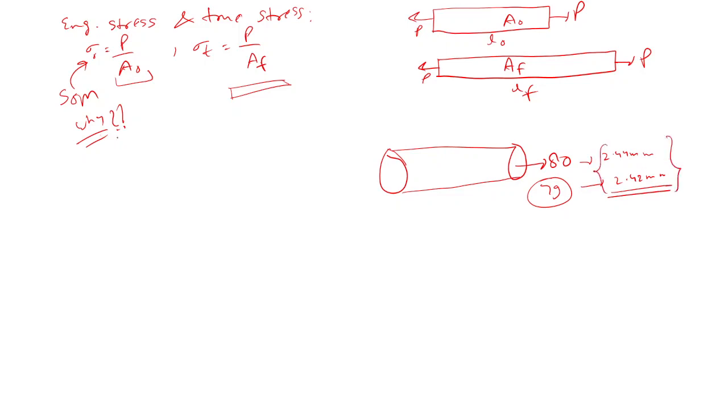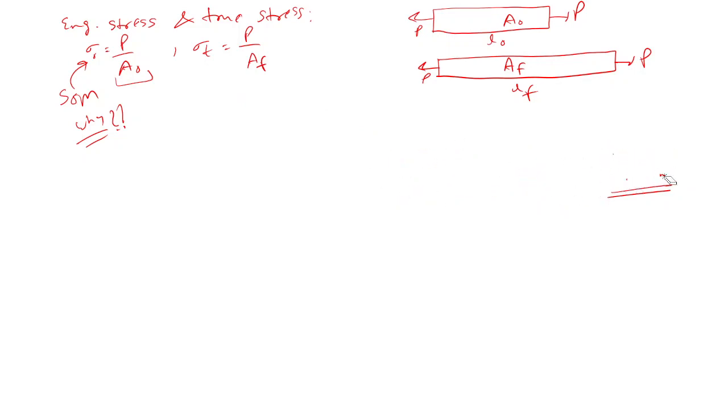So that's why in strength of materials, because our loading condition is usually in the elastic zone, due to the low loading we can use this, and the error in the answer is very comparable to the actual answer. But in the metal cutting and metal forming portion we will go with true stress only. But here, let's suppose any problem is written in strength of materials, like a steel body, but they have given a significant amount of change, then at that time you have to take true stress, right? Got what I'm saying or not?